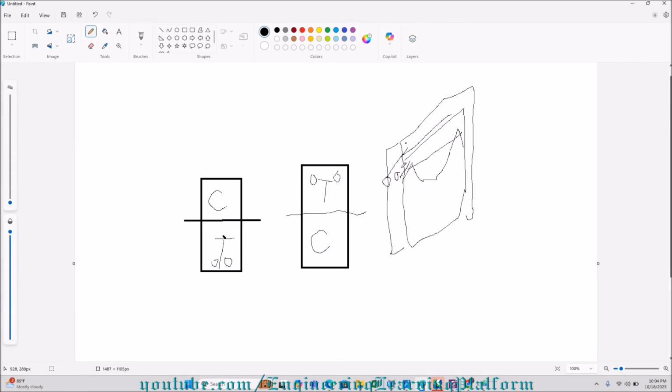So if I talk about the wall section, you need reinforcement in top, but for another case you need reinforcement at the bottom. So that's why we go for reinforcement in two layers. I hope I made a point over here.